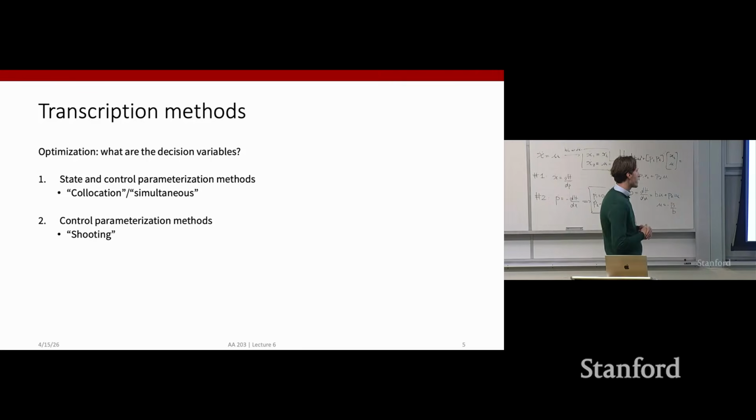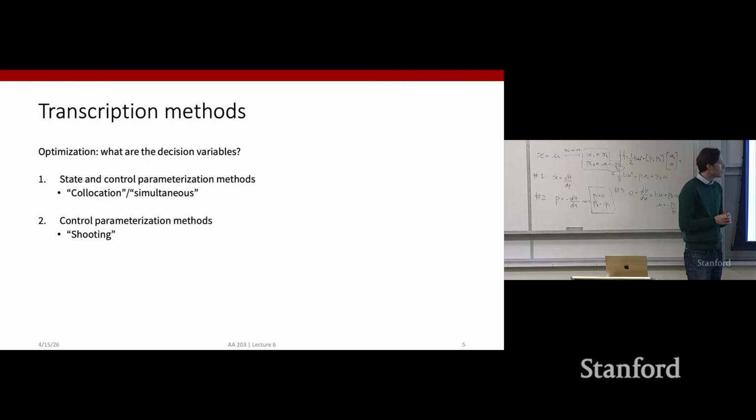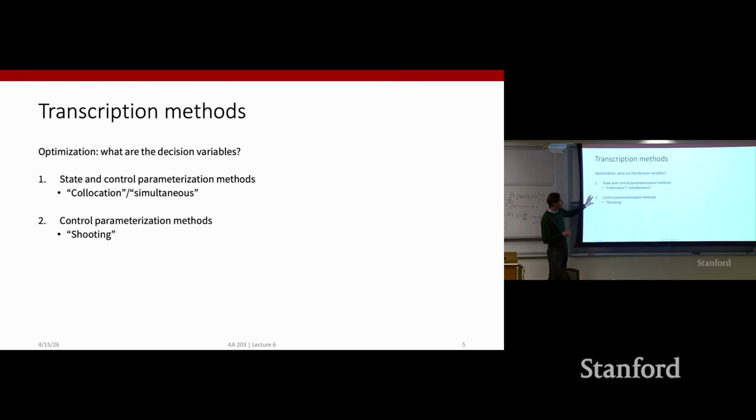At the same time, because the states are only recursively computed through the unrolling and propagation of our dynamics, enforcing constraints over states is definitely more challenging. Because if you imagine the other approach where both states and controls are optimization variables, we can directly impose state constraints by just introducing a new constraint on an optimization variable. We'll see this more in the next slides, but here just to give you a feel of the pros and cons of different methods.